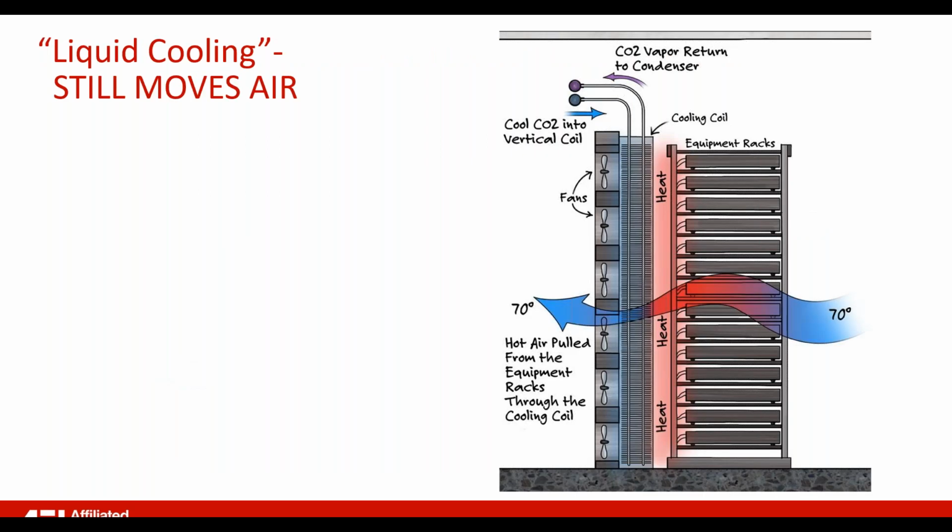And then with some of the higher density requirements that, as Daniel was talking about previously, and as we're seeing in the marketplace today, there's the use of almost point-level cooling at the rear door of a cabinet, whether that's water or refrigerant or CO2. There are various means and methods and systems out there that can provide this type of direct rear door heat exchange environment.